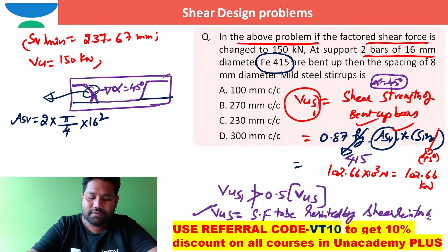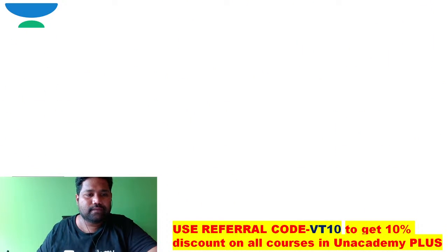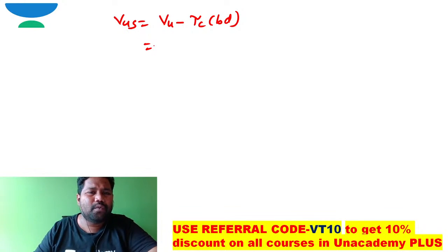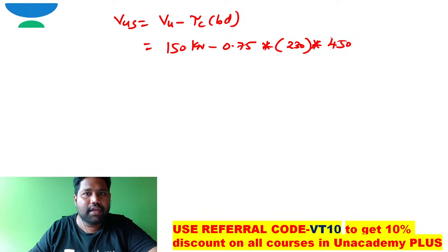VUS is equal to VU minus tau C times b d. VU is 150 kilonewtons minus tau C 0.75 Newton per millimeter square into b, which is 230, and effective depth, which is 450.